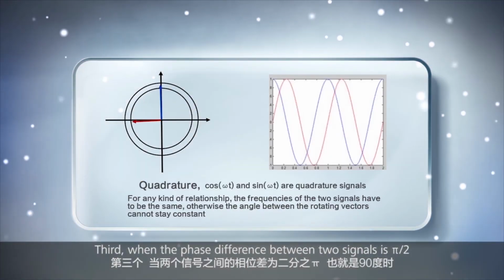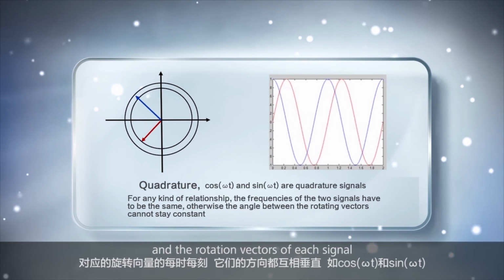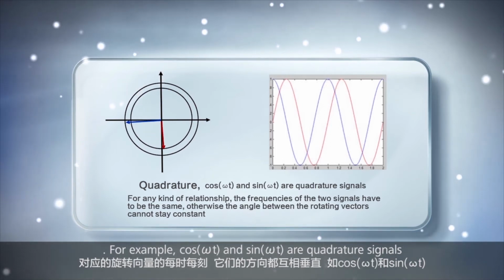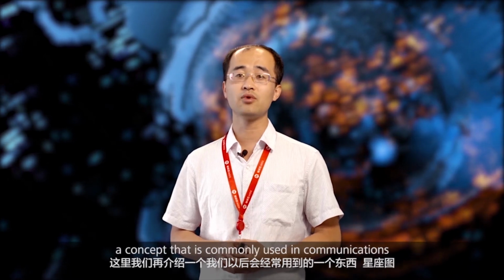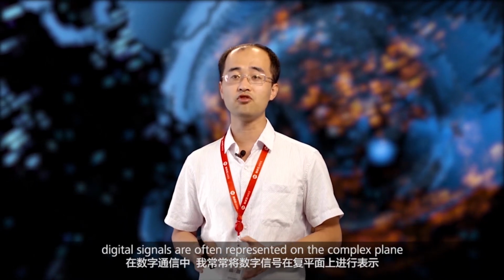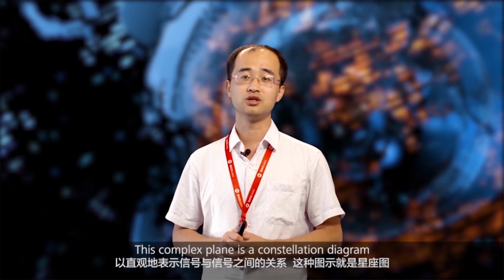Third, when the phase difference between two signals is π/2, we say that they are quadrature signals and the rotation vectors of each signal are perpendicular to each other. For example, cos ωt and sin ωt are quadrature signals. Next, let's talk about constellation diagrams, a concept that is commonly used in communications. In digital communications, digital signals are often represented on the complex plane to visually illustrate the relationships between signals. This complex plane is a constellation diagram.